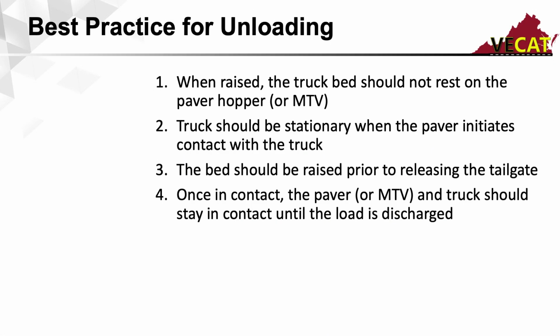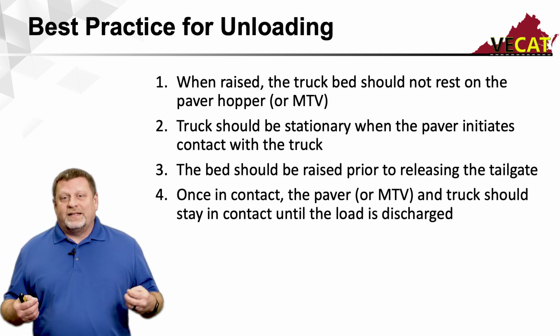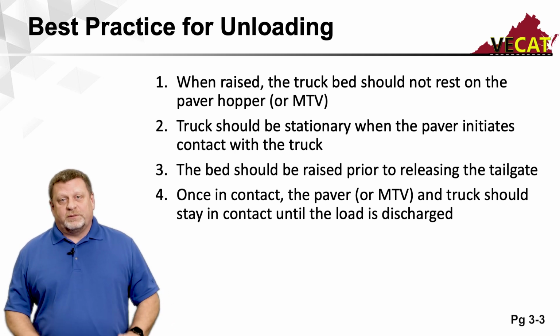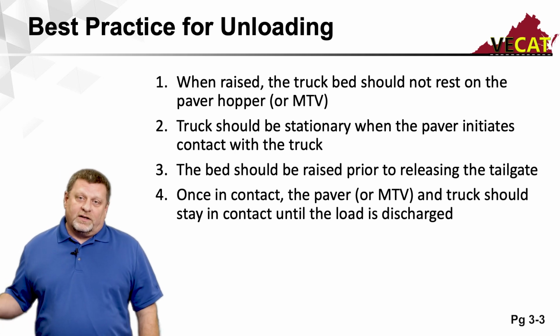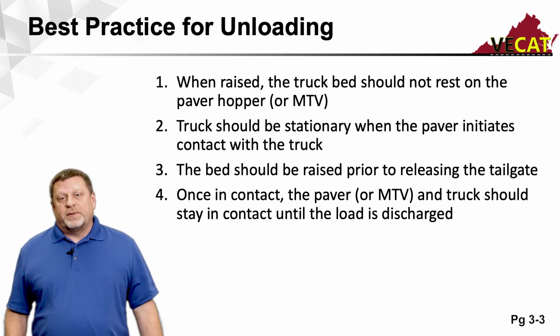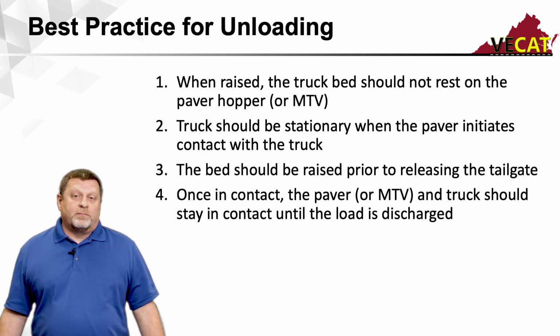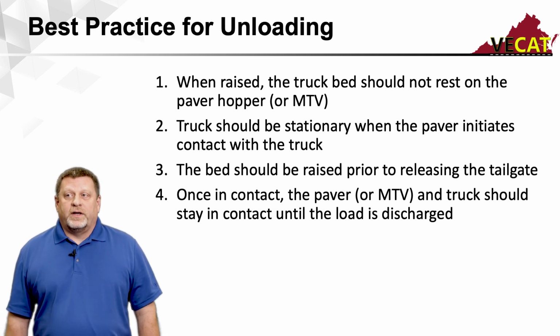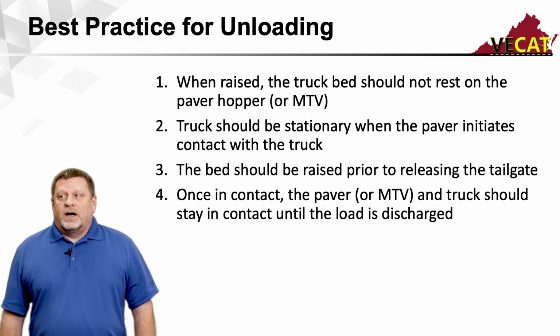Best practice for unloading: when the truck bed is raised, it should not rest on the paver hopper or the MTV hopper. If the bed of your truck is hitting the metal of the hopper of the paver, with that force as it pushes down, it'll cause the back of the paver to lift up. When the paver lifts up, it's going to increase the amount of material going underneath your screed, and it's going to create a bump that'll stay in that pavement forever. You won't be able to roll that out. So it's very critical that when you're dumping your load into the paver, you don't have the actual bed of the truck contact the paver hopper.